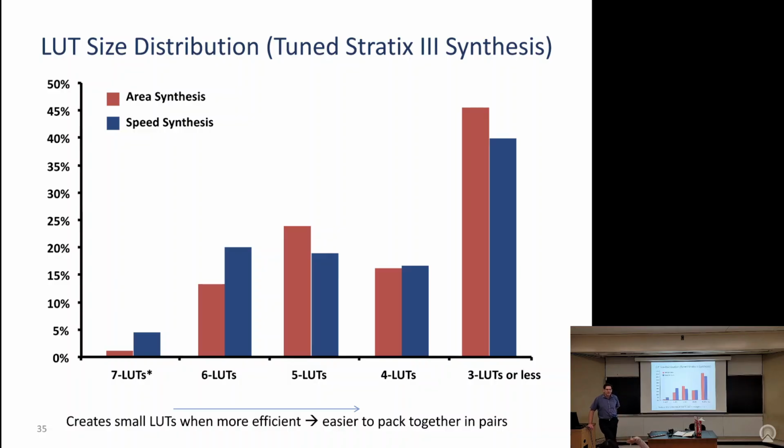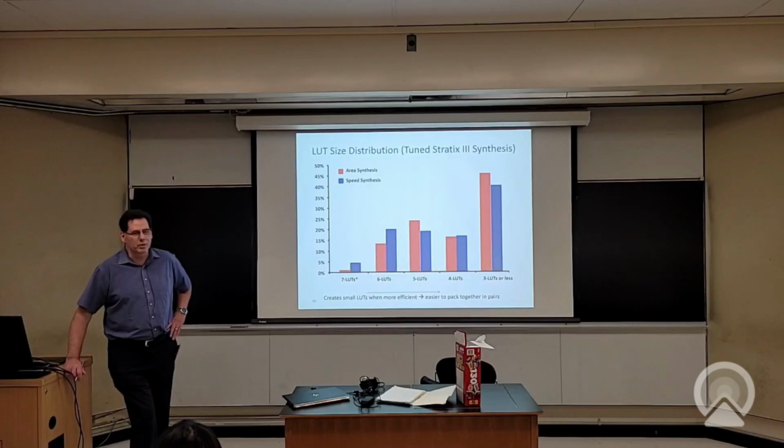Especially we have the crossbar block and the CLBs. Yeah, you could reuse that. But once you reuse that, that crossbar was basically allowing you to come in on different pins, which made it much easier to route. Once you use that crossbar to do switching, you've got to come in on specific pins. So now it's much harder to route. So then you wind up adding usually a lot of flexibility to the rest of your routing. And then you have to evaluate, is that now more expensive than just saying I'll build more LUTs?